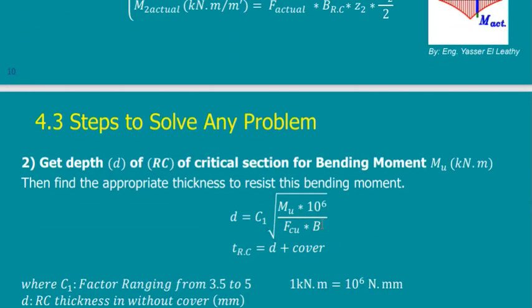So you will get the D, the depth of your foundation. Of course, you are using the maximum moment, so this is the maximum depth that you require. Add the thickness of the cover, which is usually 7 centimeter in the Egyptian market. So add 7 centimeter to this D, then you get the number. Is this number going to be taken as it is?